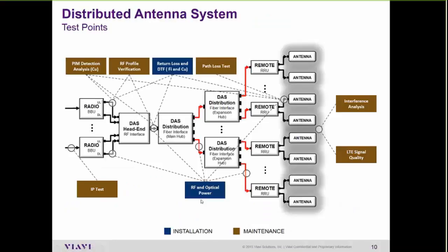So as far as power setting goes, there's probably only a couple places today you're going to directly measure power. Today with remote radio heads out at cell sites, the radios are up on top of the tower. And unless you have a tower crew, it's going to be very difficult to get somebody to climb the tower and take the test set to the top.